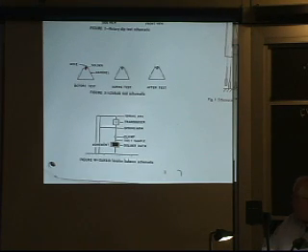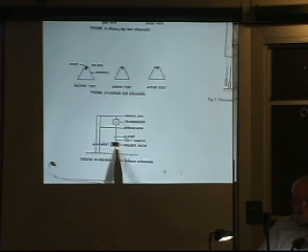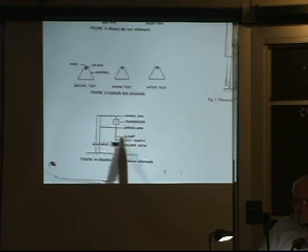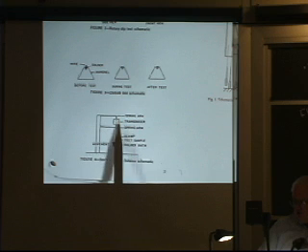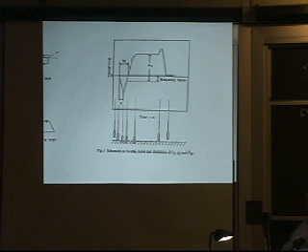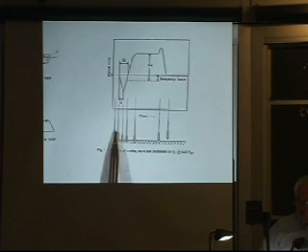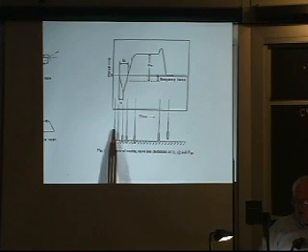It doesn't show everything, but it's got controlled crosshead movement, and the thing comes down and it weighs. There's a transducer in here, so you're actually going to measure the force on the wire as it goes in, and you will get a curve that looks something like this, where this is the wire that you wanted, the copper or whatever that you freshly cleaned, hopefully, and you're going to push it in. As soon as it hits the surface, there's nothing that happens.